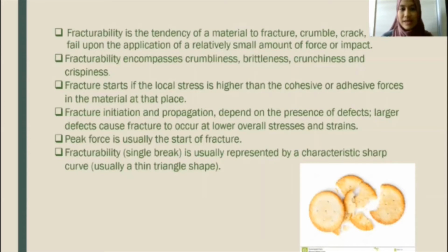A biscuit is brittle if it is liable to fracture when it is subjected to stress or any load. It has little tendency to deform or strain before fracture and usually makes a snapping sound. Fracture starts if the local stress is higher than the cohesive or adhesive forces in the material at that place. It spreads spontaneously if the deformation energy that is released when the material fractures is at least equal to the energy needed to create a new surface.